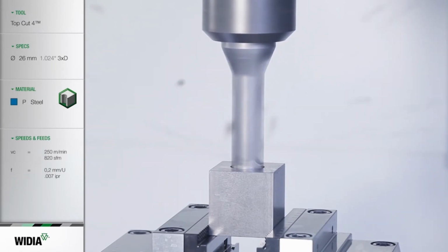In this trial, you can see that we are machining a steel cube, and everything is almost ideal. The only thing not ideal is that we are not using coolant here. In all cases of drilling operations, we recommend using internal coolant, or sometimes external, but not using any is not good to do.